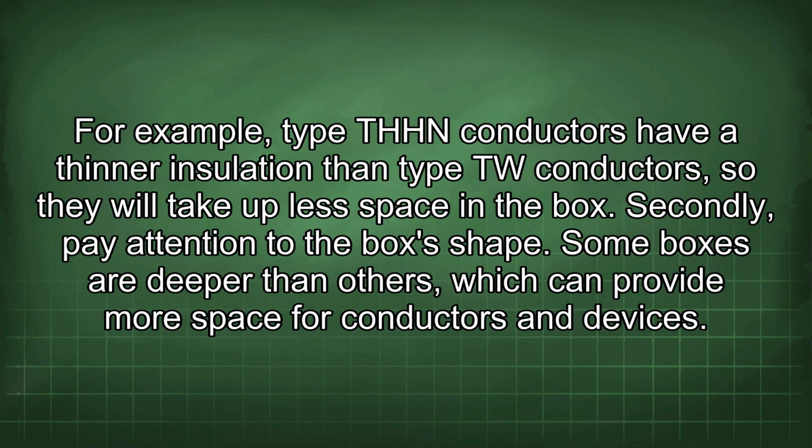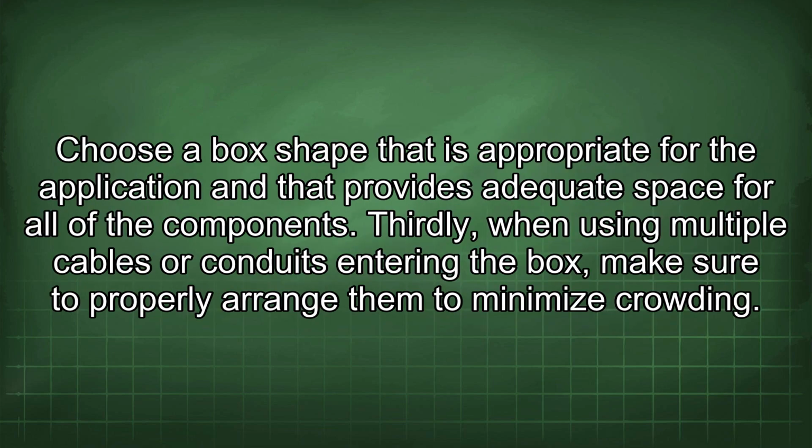Secondly, pay attention to the box's shape. Some boxes are deeper than others, which can provide more space for conductors and devices. Choose a box shape that is appropriate for the application and that provides adequate space for all of the components.